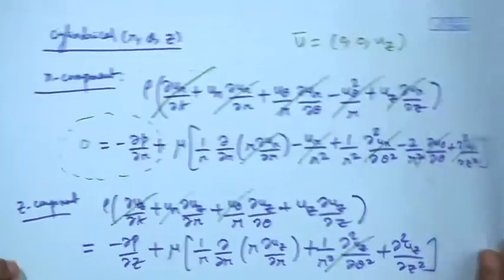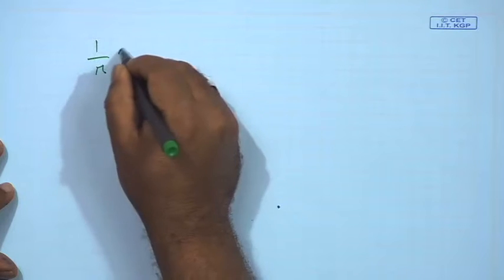But one equation we did not use yet, that is not the theta component. If you see the theta component, what you really get is the complete left hand side is 0, the right hand side viscous terms are 0, and simply we get dou p dou theta is 0 from the theta component. Nothing much. The other equation that we have not used is the equation of continuity. So, when you have unidirectional flow, what happens to the equation of continuity? For the time being, let us have this, we will revisit. So, let us go to the equation of continuity.